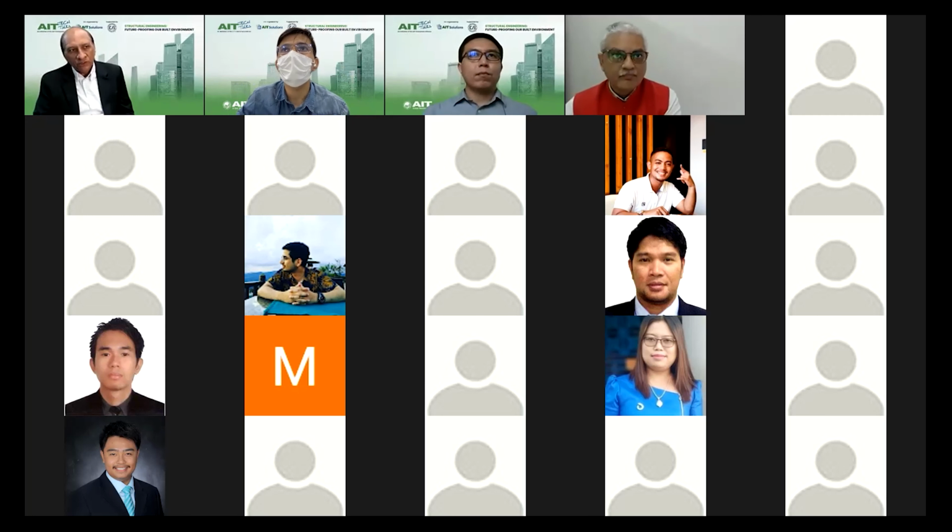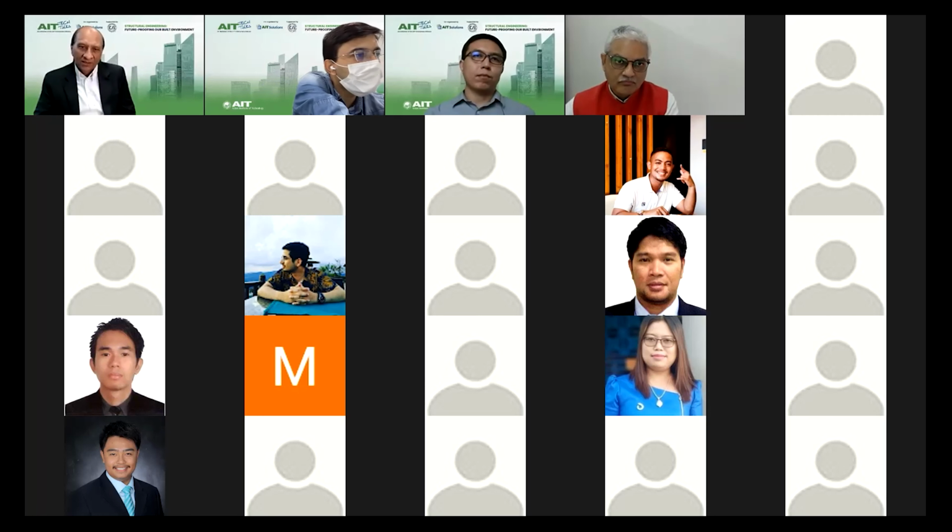For example, the most common case is the ductility requirements in the codes, which ask you to follow the ductility rules everywhere. But by performance-based design, you can find out that in some places, members which are not participating in the lateral load may not need to follow those guidelines, and you can reduce the reinforcement there. Can I invite you to say something about that? Yes, sir.